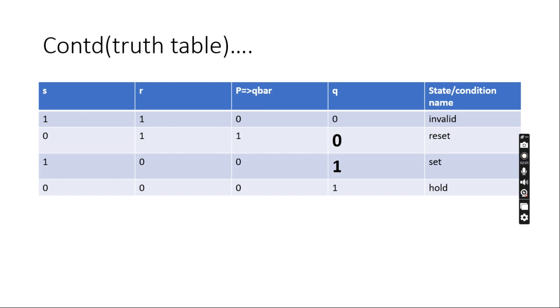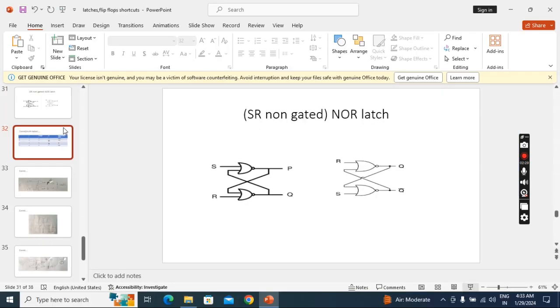So here in a NOR latch, if we keep this circuit in 1 1, it will be invalid. Whenever we want to make it useful, we have to change the input values. And one more reason: suppose initially I apply 0 0 to the NOR latch, what will happen?